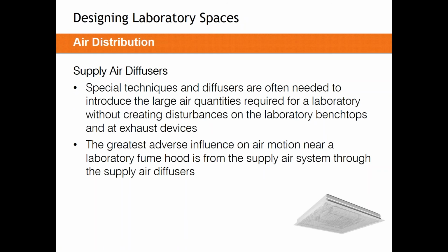Oftentimes, we'll have to treat the lab a little bit differently when we actually pick diffusers. The standard 4-way plaque diffuser or cone diffuser may not work for you in these instances. They'll have great mixing characteristics, but they'll often have very high throw values that are not going to work in our lab environment. Now, in saying that, I have personally been in labs that do work with 4-way diffusers in them. I know they're very cost effective and it's a very common look throughout a lot of buildings. It just may not always work for you.